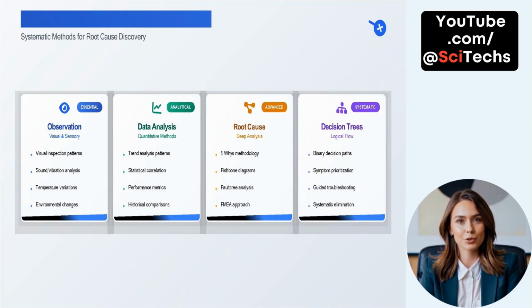Systematic methods for root cause discovery. To address failures effectively in semiconductor manufacturing, systematic methods for root cause discovery are essential. One foundational method is observation, which relies on visual and sensory techniques. This includes recognizing visual inspection patterns, detecting abnormal sounds or vibrations, noting temperature fluctuations, and identifying environmental changes. These are frontline indicators that something has gone wrong.